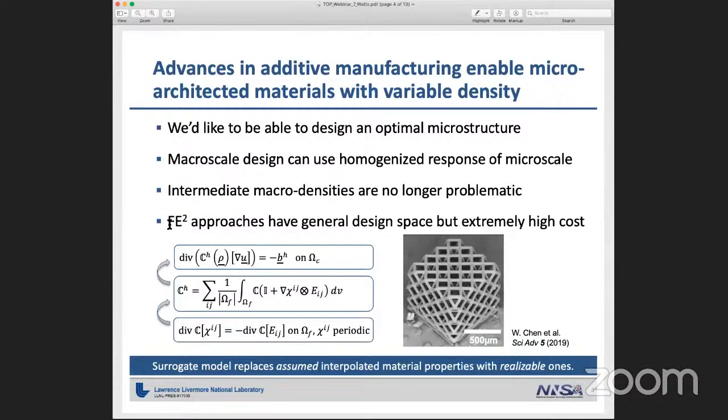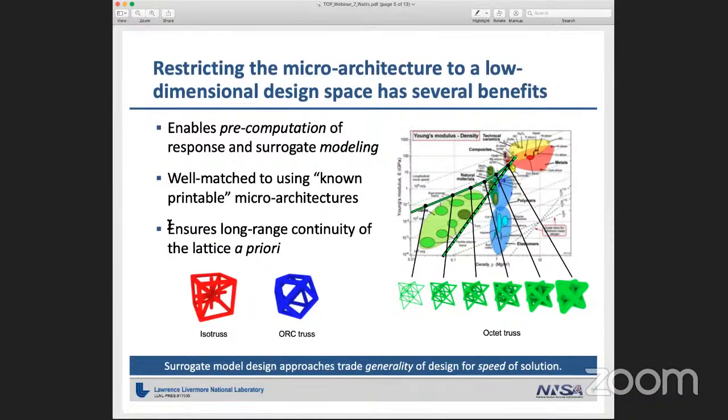So the really full power way of designing optimal structures like this is kind of a full topology optimization: do a macro scale topology optimization, and also micro scale topology optimization. So at every point in the macro domain, you can design an optimal microstructure. That's certainly been done. It's been described in the literature. The trouble is it's expensive, especially in 3 dimensions. And it's just an expensive problem. So we'd like to do something that's a little bit cheaper so that we can do it more regularly to solve kind of everyday problems.